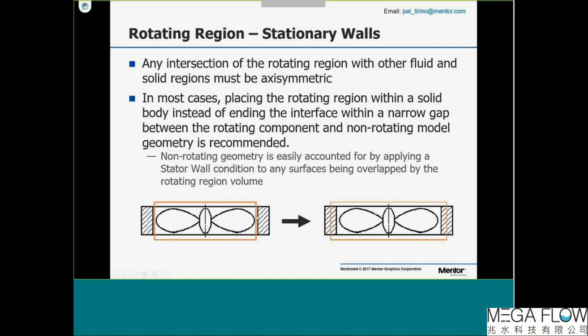And that would be the same on the other side of the interface to the solid. So I usually go by 4 cells. I would say you want at least 4 cells between each interface, okay? That would mean in this very small gap, we need to put 8 cells to really calculate this reasonably, okay?